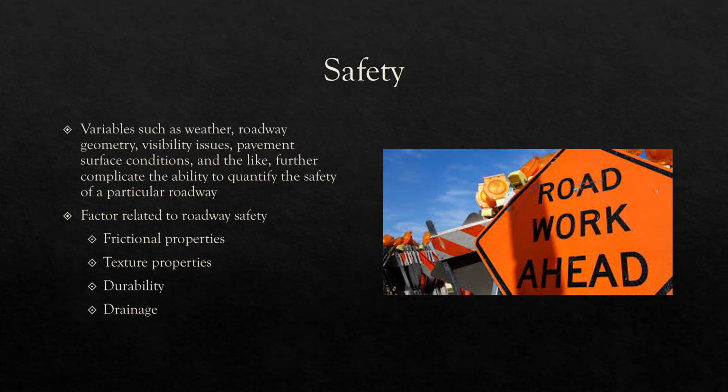Durability. Pavements, by their very nature, are completely exposed to weather and are subjected to potentially millions of wheel passes over them during their lifespan. The repeated application of wheel loads tends to wear down or wear away paving materials. Weather, likewise, can slowly wear away pavement surfaces through oxidation, erosion, or freeze-thaw related deterioration. There must be a balance between providing the necessary frictional characteristics and providing a durable, long-lasting surface while not ignoring the importance of cost. And lastly, drainage.